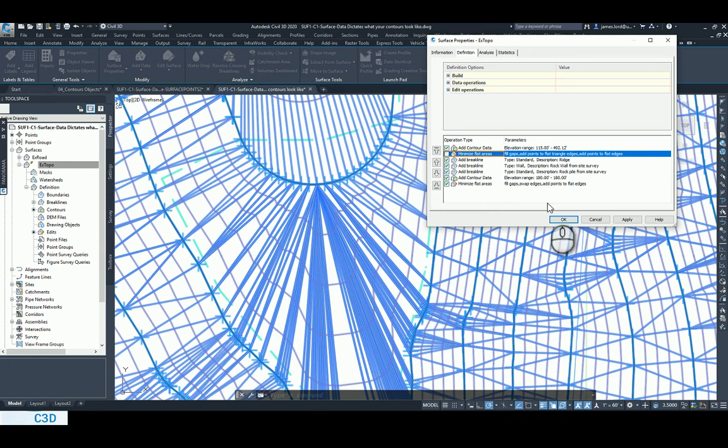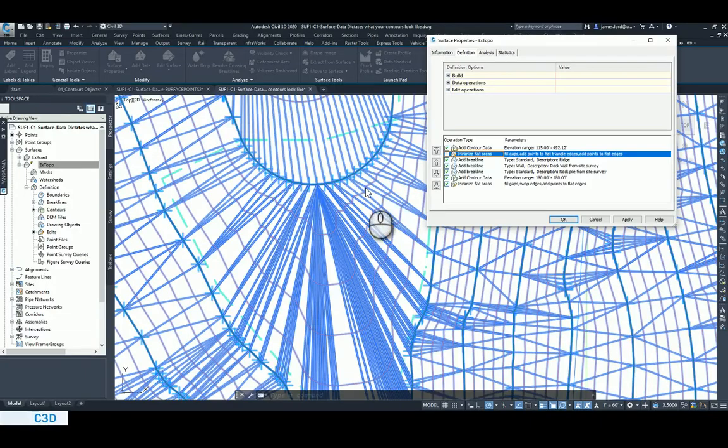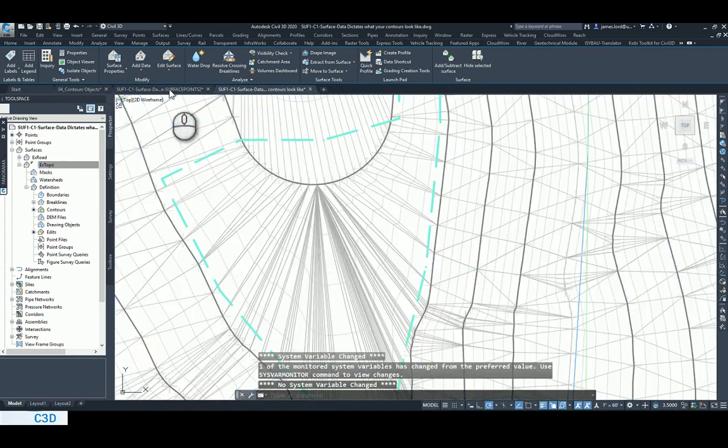All right, so what else is next that we can look at here? Oh, I should go back to that. You can see that the contours are looking a little better, but they are using all the vertexes that are along this line, which is why they don't look so good. So my suggestion is basically to draw in the lines manually. And do you have to draw every line? No. Please, no, don't draw every line.